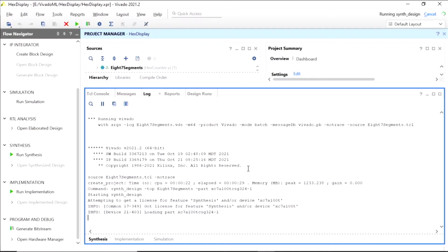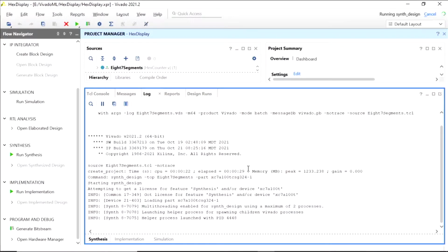I've been in that situation a number of times with Vivado, that you have to treat it kind of gently, let it finish most of the time, because that's when you start getting stuck. Is when you interrupt it, and sometimes you just can't get away with interrupting it. And in that situation, you gotta delete all the files that aren't necessary to the project and start fresh.